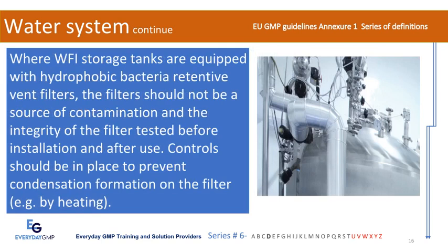Where WFI storage tanks are equipped with hydrophobic bacteria retentive vent filters, the filters should not be a source of contamination and the integrity of the filter tested before installation and after use. Controls should be in place to prevent condensation formation on the filter, e.g. by heating.